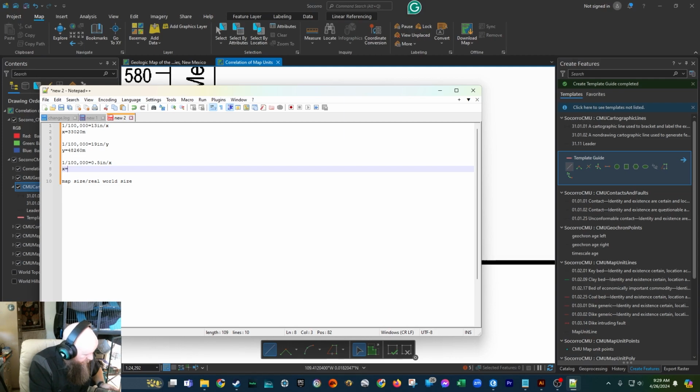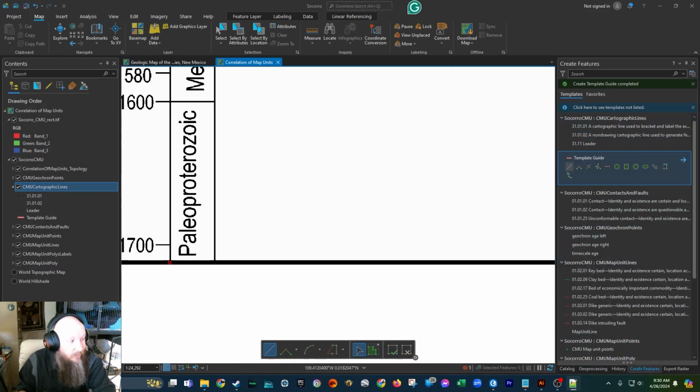So at 1 to 100,000, a 1/2 inch box is 1270 meters. So that's what we need to input into our directional and absolute XY, 1270. And the reason why I talked about our delta XY is for this factor right here. So I want to throw a directional, so Shift A. Oops, activate the right window, Shift A.